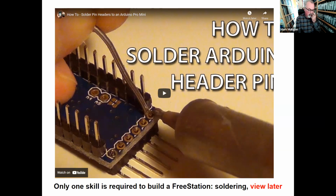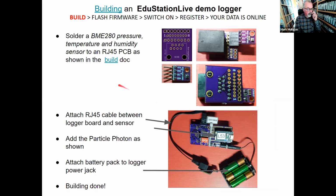Soldering is important because you need a good connection between the different components. The key thing to avoid is bridging, when your solder connects two pins together. That's obviously a bad thing, and you need to remove excess solder if you end up with that. So that's a good YouTube video, just a couple of minutes long, on how to solder.